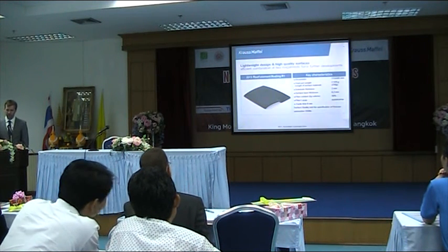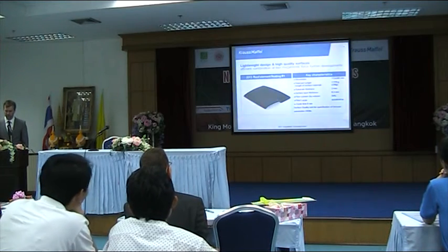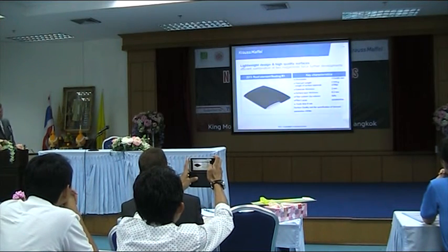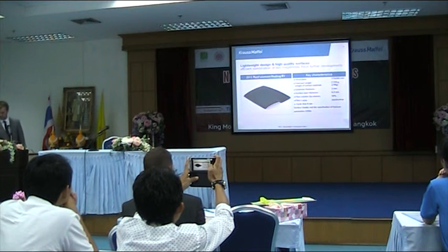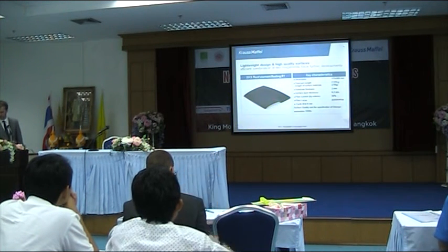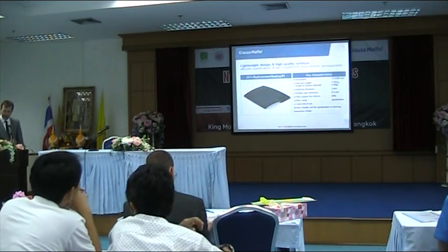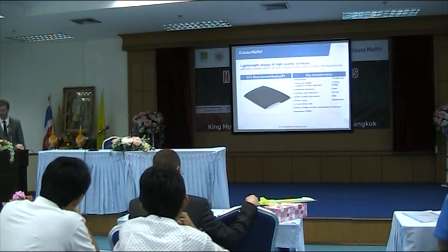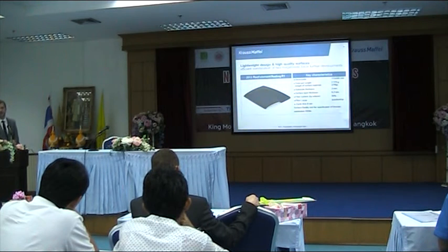It's the roof element of the Roadster R1, and there are some details of the part itself. Substrate thickness about 2 millimeters, surface layer thickness 0.2 millimeter, fiber content about 50%, and fiber layout quasi-isotropic. The cycle time is 6 minutes.